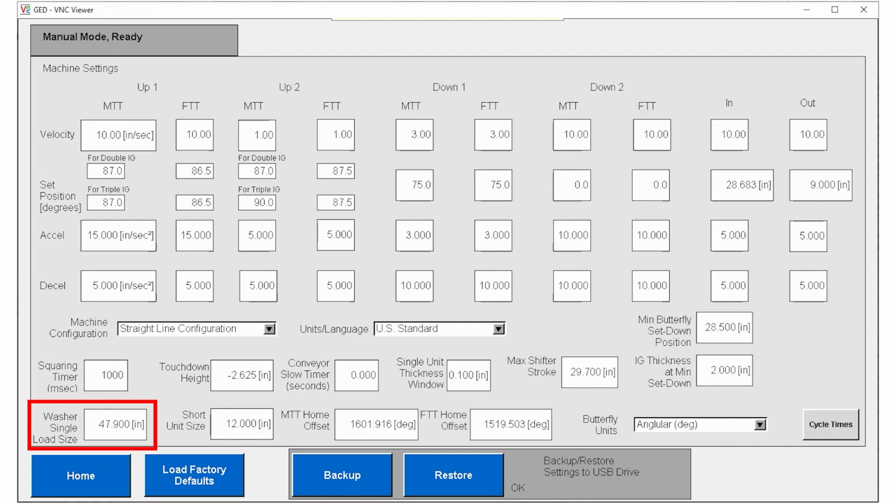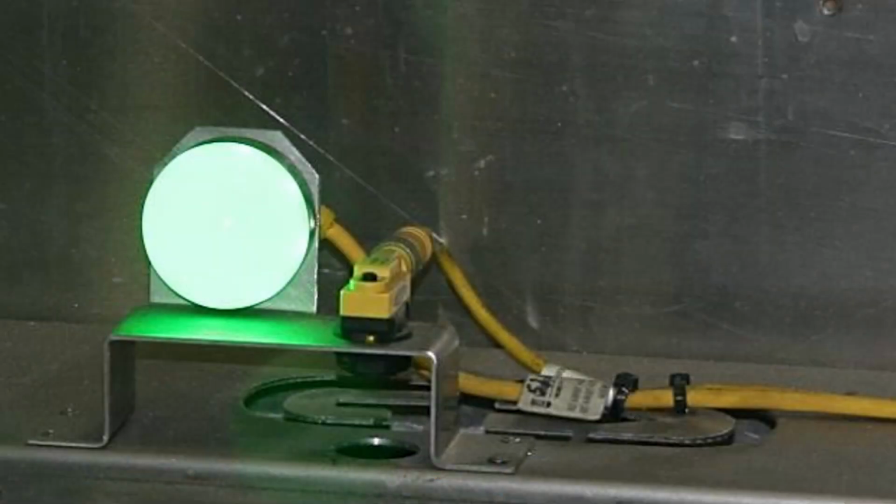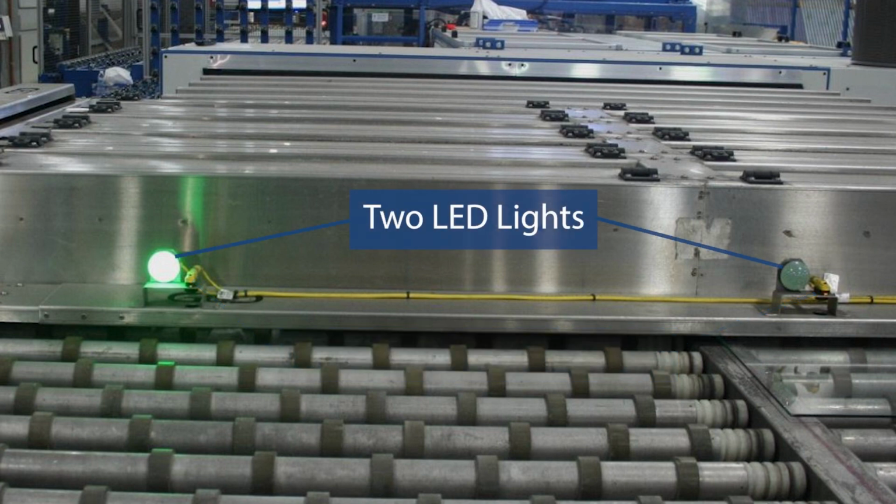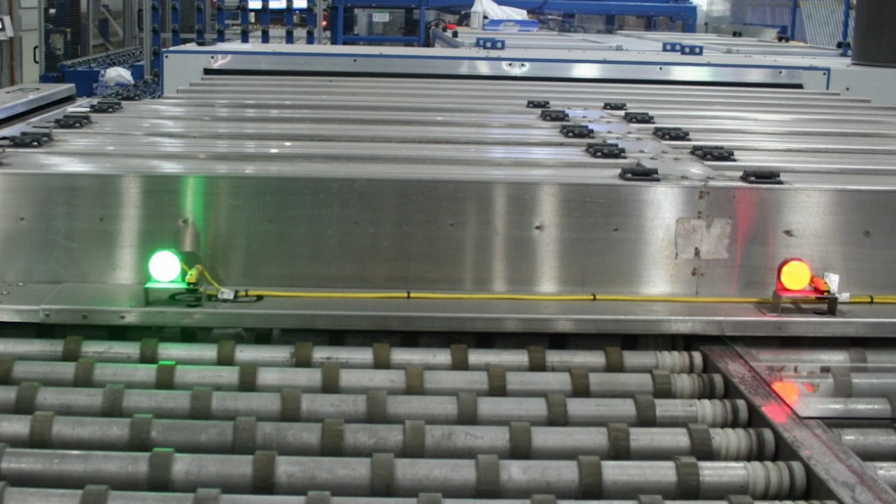The next parameter we'll discuss is called the washer single load size. This parameter helps the PLC interpret the input signal received from the washer loading sensors. There are two ultrasonic sensors located at the entry of the washer. They detect where and when a light has been loaded. There are also two LED lights. The lights turn green to indicate where the next light is expected to be loaded. If the light is fed into the wrong location, the light turns red and puts the washer into a creep mode.